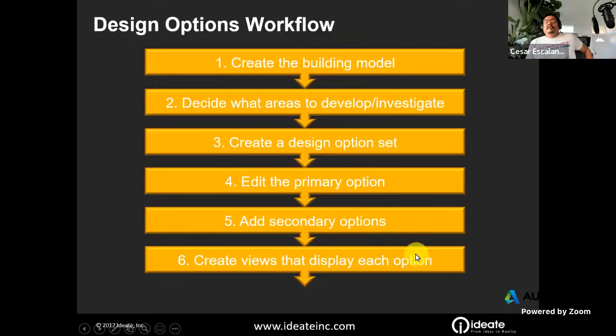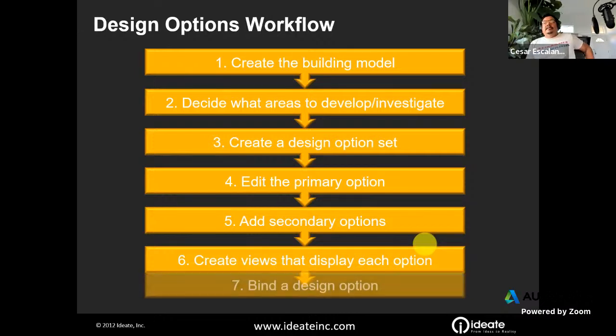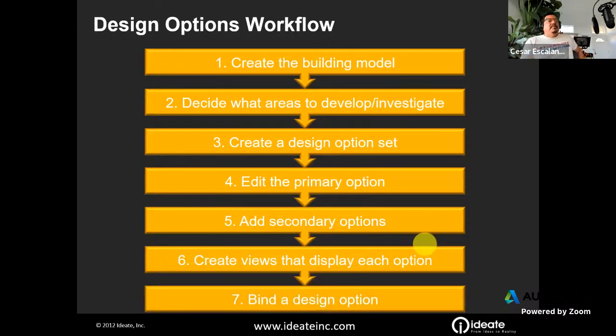And once you have decided what option you want to keep, you can save this model somewhere else as a backup and accept the primary option. Binding a design option means getting rid of an option set and display only the option, the preferred option from the client.